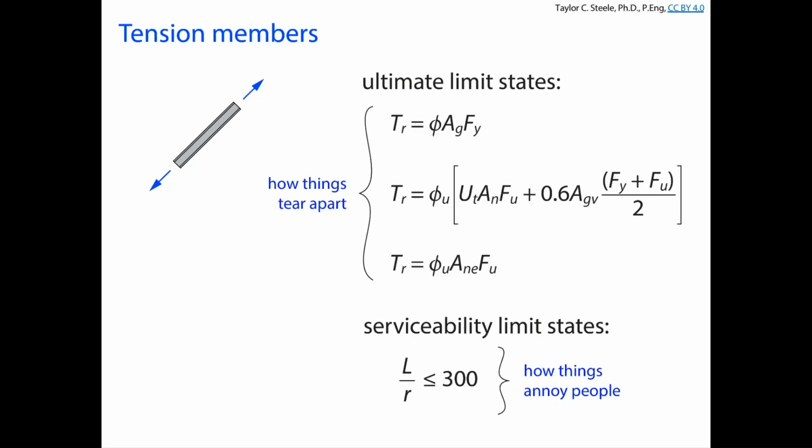We've got the potential for the tension member to fracture at the net section at the connection. And so we've got two ways we can have fracture happening. One is the net section fracture, where we just go straight across a tension plane that accounts for the loss of bolt holes or the loss of some steel being affected in tension through the fact that we only have some of the elements connected sometimes.